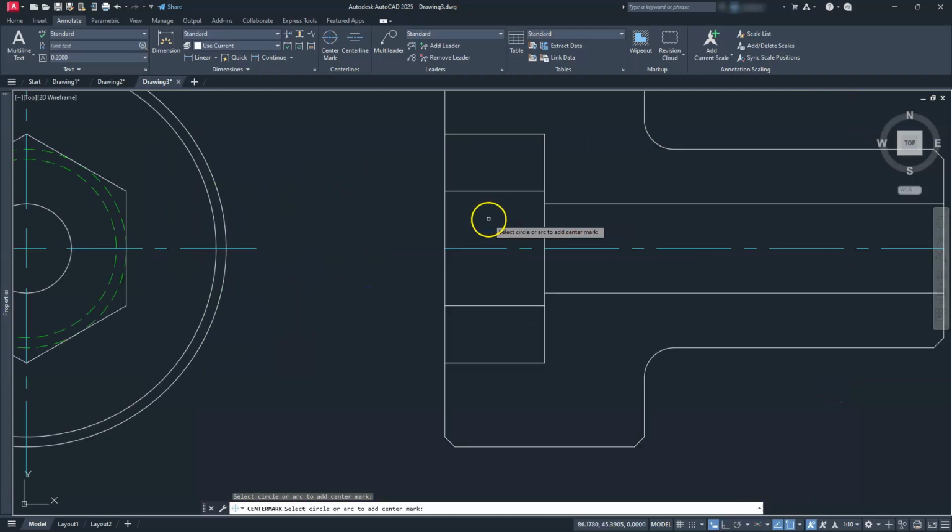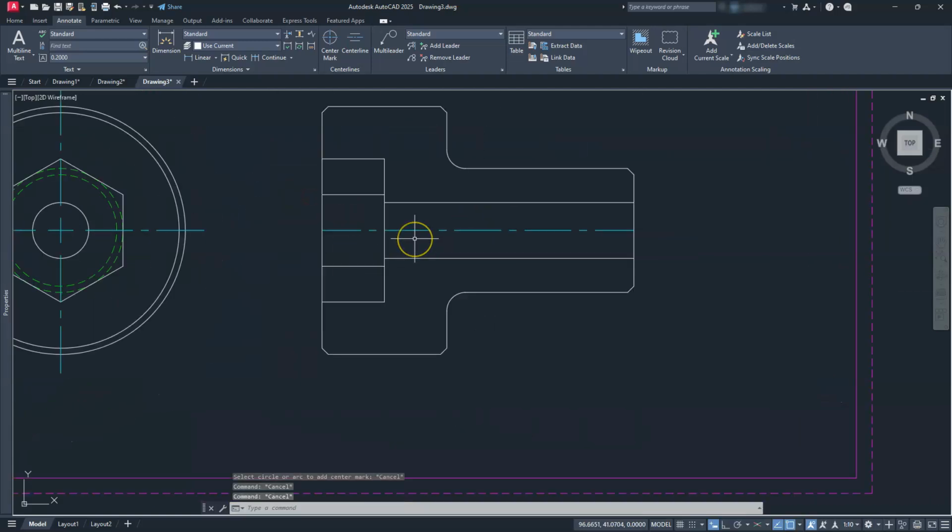And then on this side, I'm going to extend these, right? So I'm going to use the lengthen command. So I'll just use LEN. I'm going to select it by a delta. So I'll select the word delta here. It's asking me to enter that delta. I'm just going to click from that quadrant to that endpoint. And that's going to allow me to click here and here.